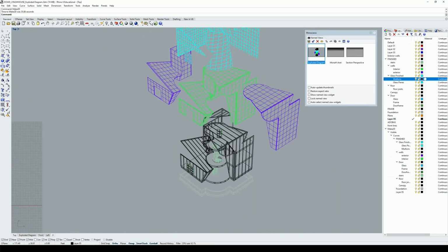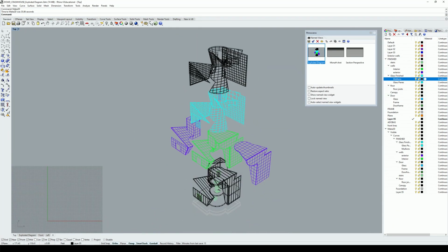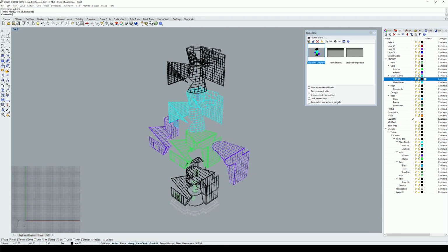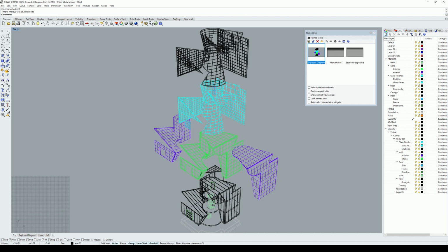Obviously there's some lines that need to be cleaned up. But for the sake of today's drawing, I'd like to show you a few shortcuts that you can do in Rhino to help speed up this process. Make a new layer, go to the New Layer tab up top, and type in, call this Boolean Curve. Now this will be extremely helpful for those who have framing and holes. And make sure you change your active layer to that layer we just made. So I move the check mark down by clicking on that row on the layer that I want.